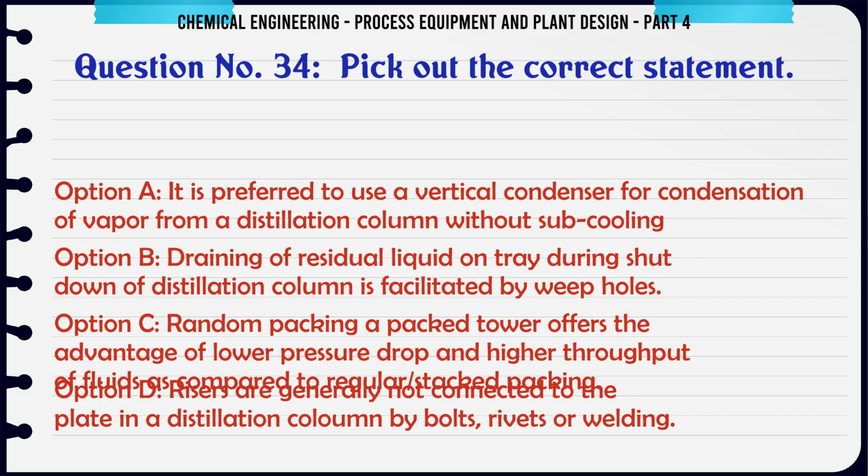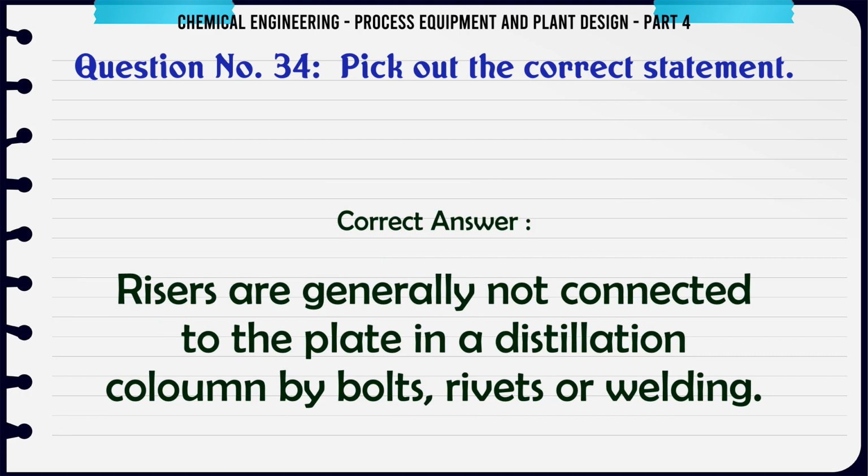B. Draining of residual liquid on tray during shutdown of distillation column is facilitated by weep holes. C. Random packing. A packed tower offers the advantage of lower pressure drop and higher throughput of fluids as compared to regular stacked packing. D. Risers are generally not connected to the plate in a distillation column by bolts, rivets or welding. The correct answer is risers are generally not connected to the plate in a distillation column by bolts, rivets or